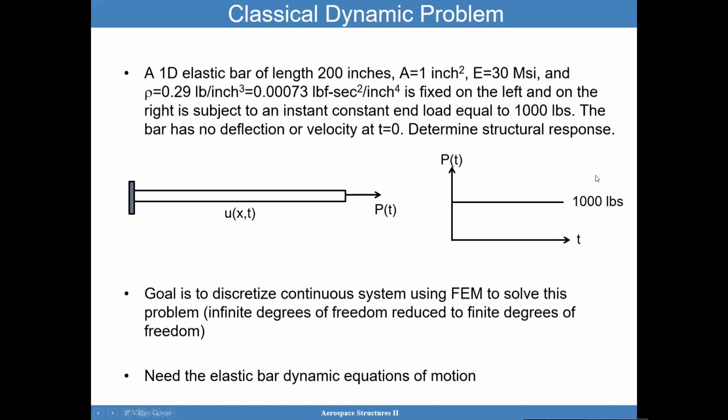Over long time. And again, we could solve this in an exact way using the Fourier series approximation to this function. But in this problem, we're going to use finite elements. And I'm going to show you in a very general way how you can discretize this differential equation that corresponds to this bar.